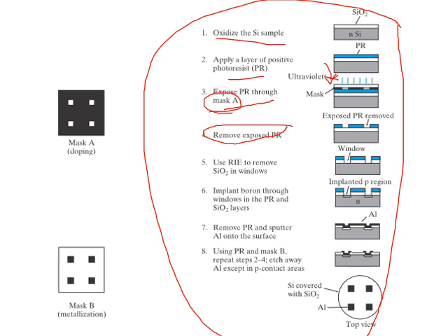Then a window is created, implantation is done. Implantation means what? Again we create doping, called ion implantation, so that N type material can be deposited in P type material, or vice versa, right? Then sputtering, that means metallization is done, and then connections can be taken outside.